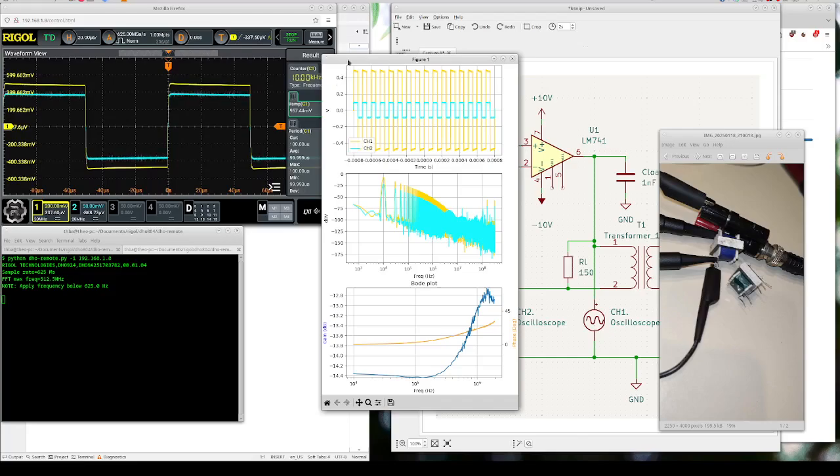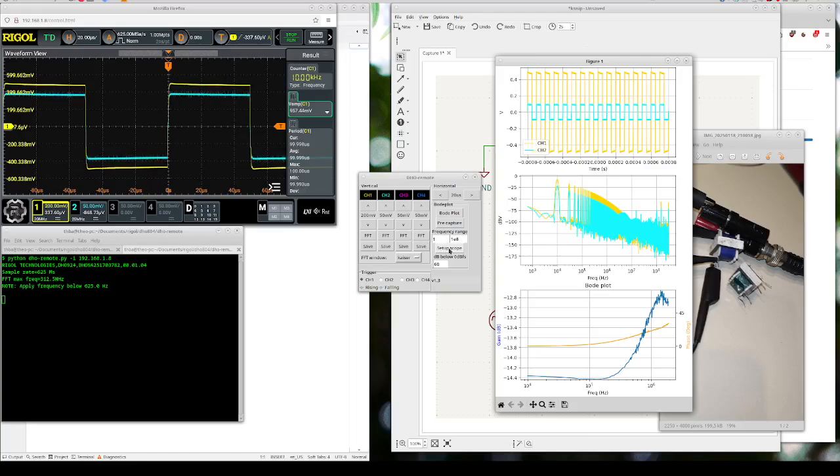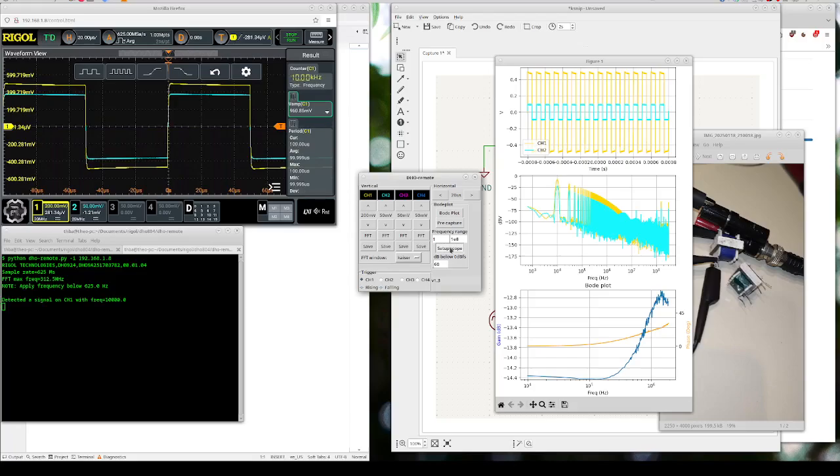And one way to deal with it is to add averaging. And instead of doing that manually, I also made a button, setup scope, and that will call the auto setup of the scope. And after that, a lot of settings are being applied. So now the averaging has been enabled here. The channel bandwidth has been limited to 20 megahertz because for almost every Bode plot you don't want to have the full bandwidth. The sampling is quite high: the highest sampling rate, 1 mega samples memory depth.